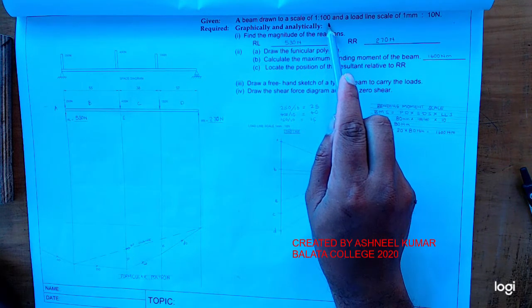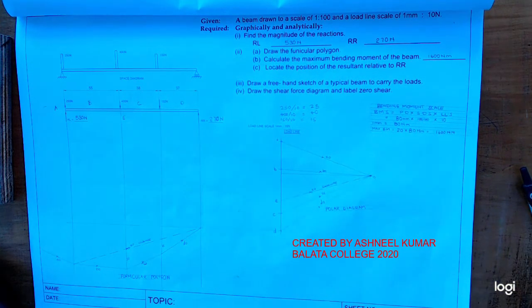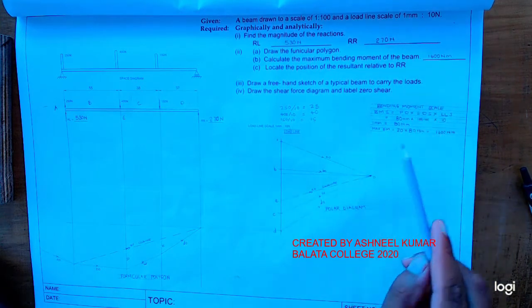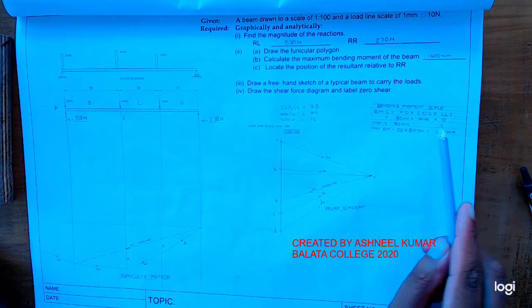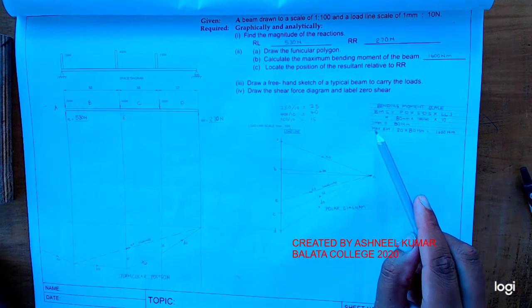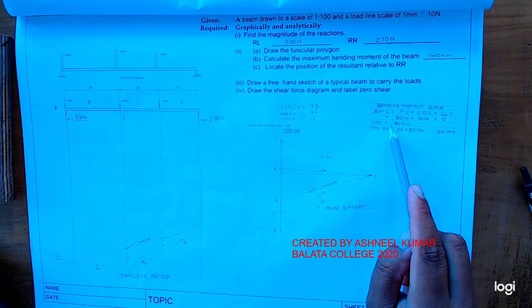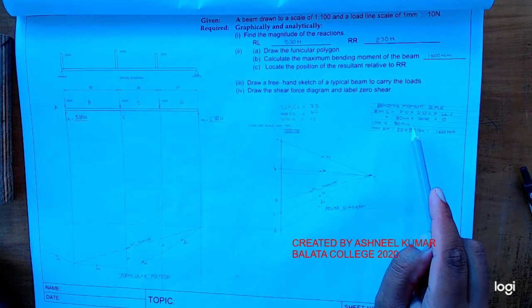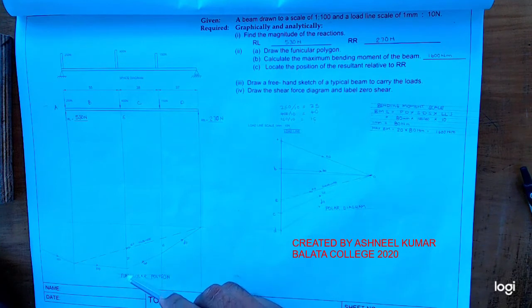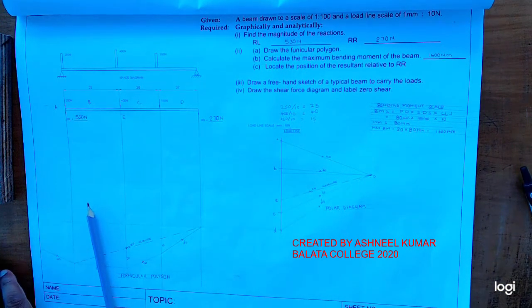So we have to have in meters. It will be 100 divided by 1000. And then your load line scale, which is 1:10. So we'll take 10 there, which means after the calculation, we are getting 1 mm is equal to 80 Newton meter. This means every 1 mm that I measure from the bending moment will be equal to 80 Newton meter of bending.